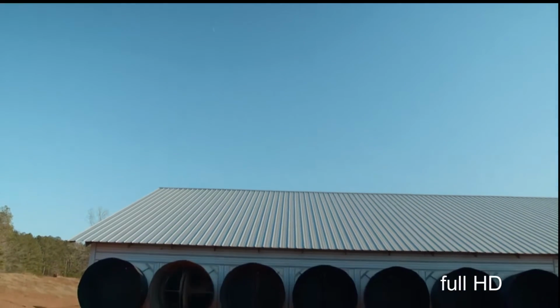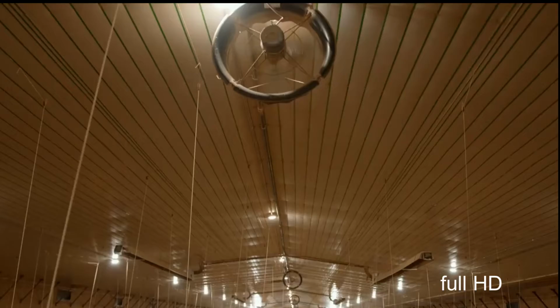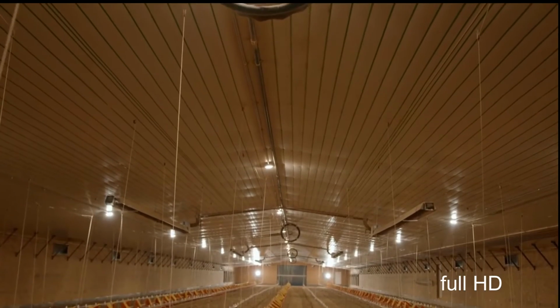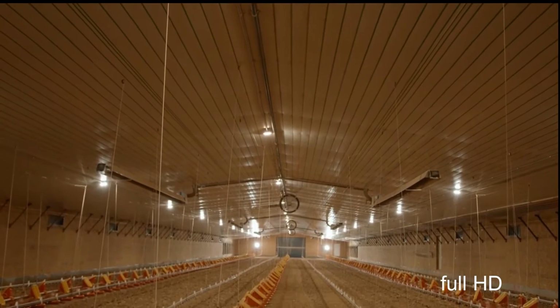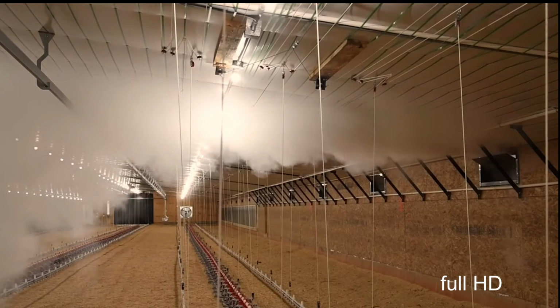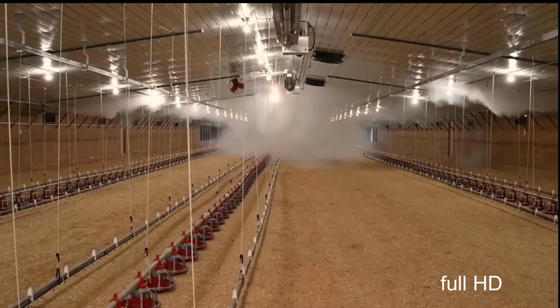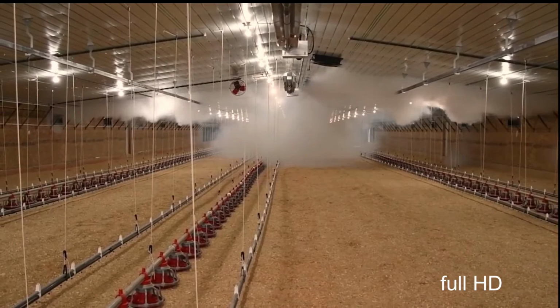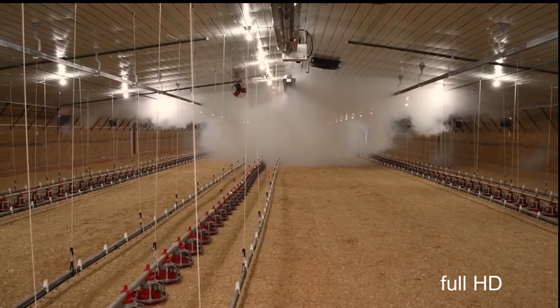We have our exhaust fans. What do they do? We turn them on and they create a low pressure zone within the house, or a partial vacuum. We also have air inlets. So the fans create a low pressure zone and we have air inlets scattered down the house. What happens with that low pressure zone is air will enter through all the inlets in the house to fill up that partial vacuum. So again, negative pressure, air comes in through our air inlets to offset that negative pressure.